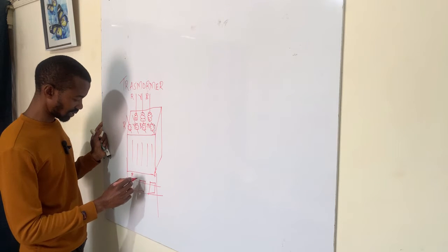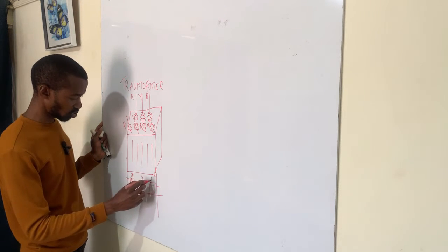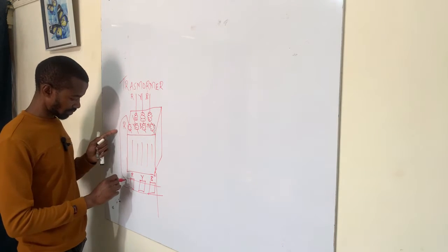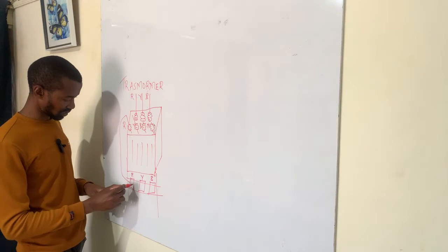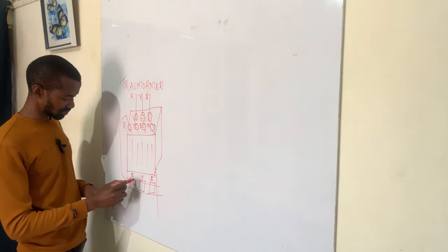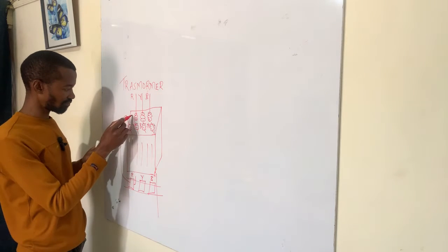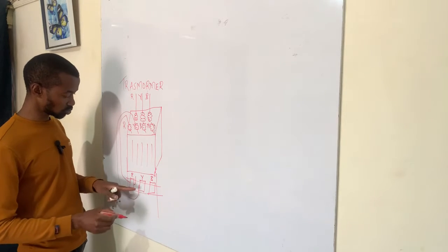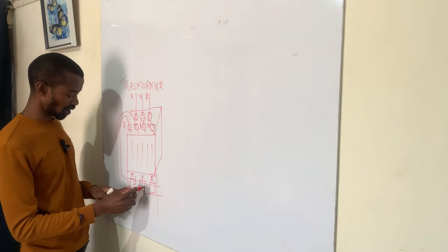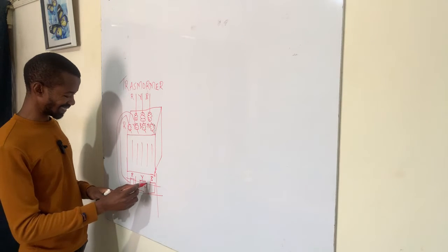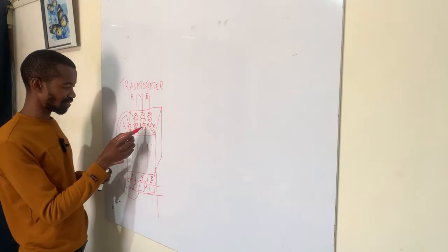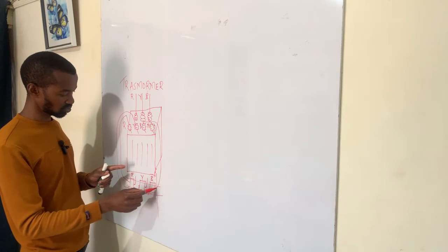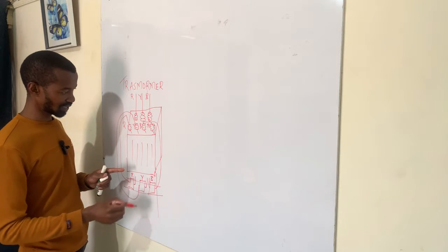And we say that electrical engineers are electrical designers. So you will have the connection for the red phase there, and then it exits, and then you will have that one for the yellow phase. It gets into the fuse carrier where you have a fuse, of course, and then it exits. And then you have the blue phase connection. The blue phase connection will also get to its fuse, and then it will definitely exit.